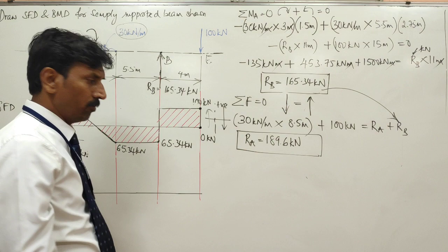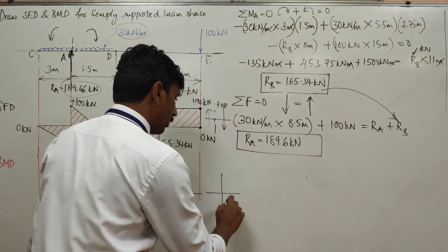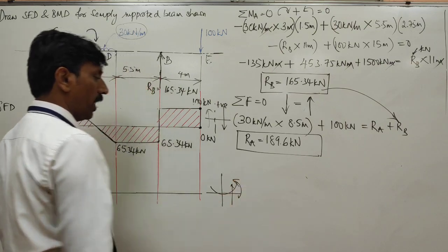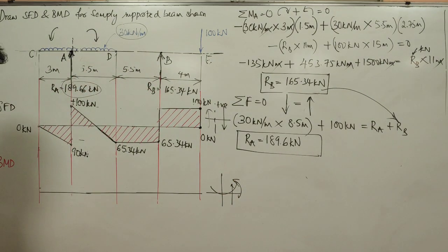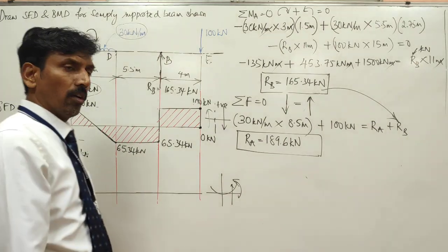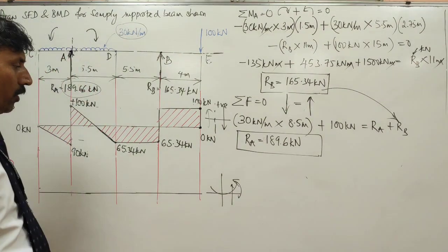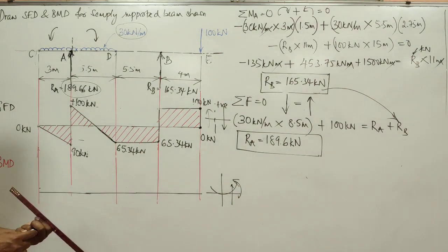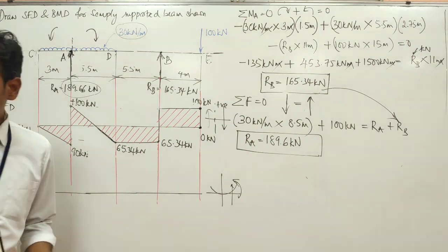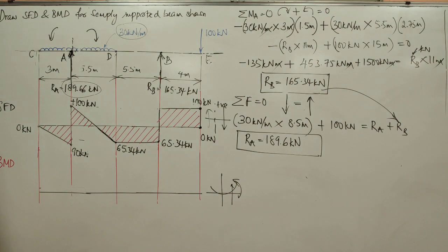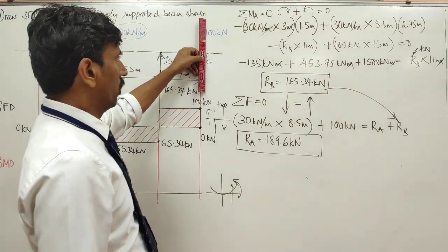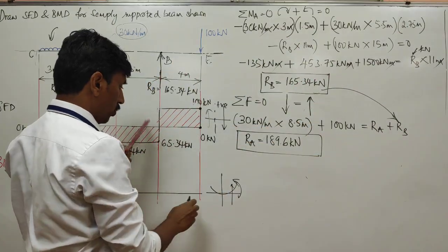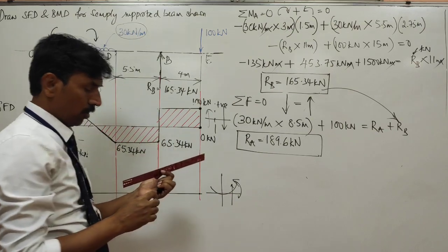Okay, as per the convention, in a beam, a force or a moment which is trying to sag the beam on either side, which is upwards, is positive. And the forces which try to hog the beam are negative. So let us start with this convention from the right side extreme end. So here I will start. Are there any forces on the right side? No forces. So I write this as 0.